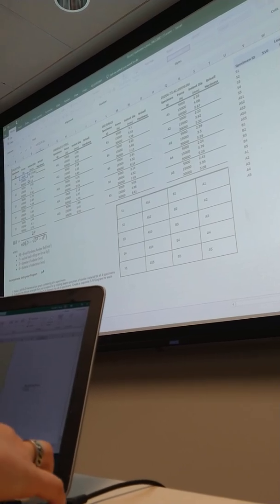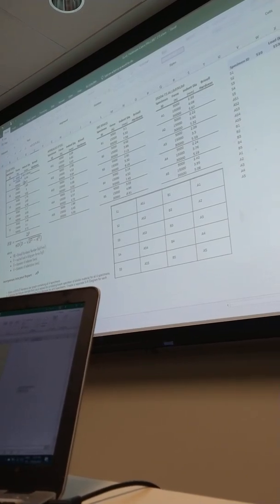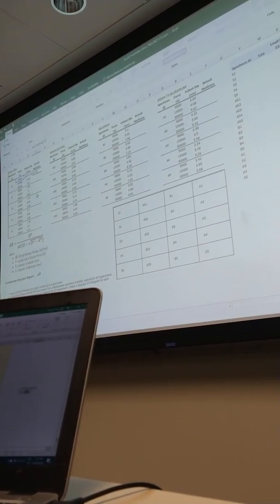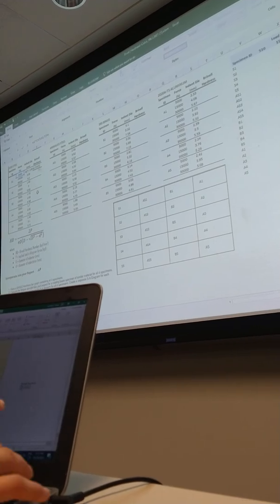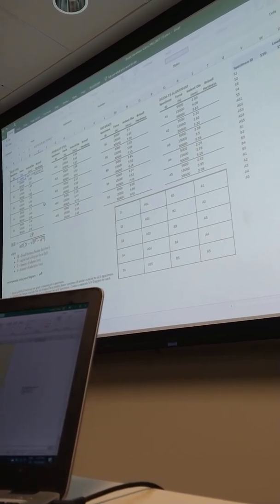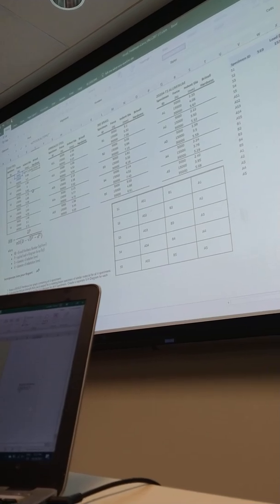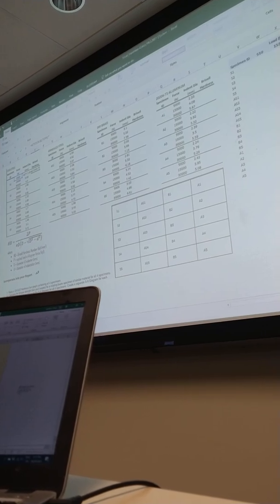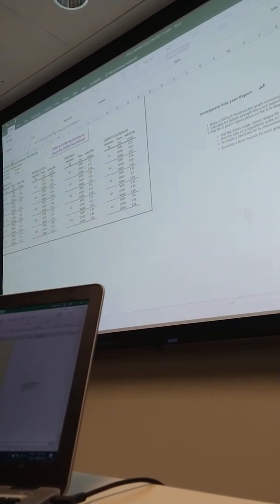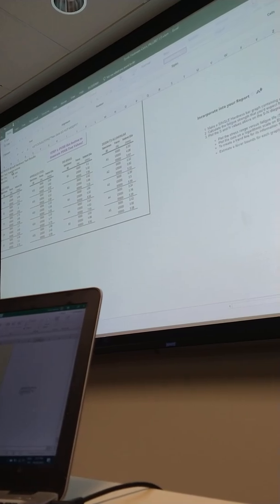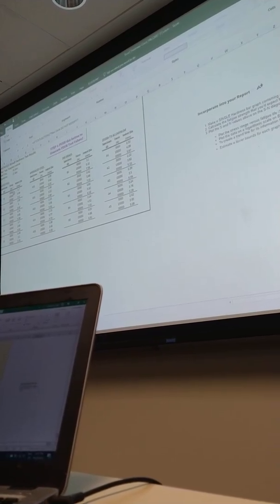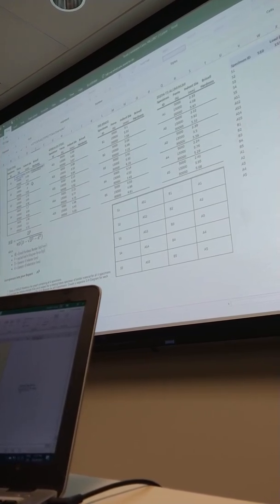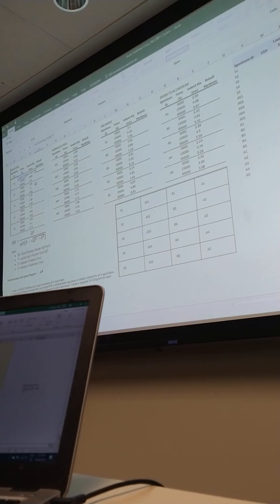So we got our force in there now. Multiply that by 2. We're going to divide by pi times our diameter. This diameter, the capital D, is the diameter of your indenter, which in this case is a tungsten ball, tungsten carbide. And it's given right here as 10 millimeters. Multiply that by 10 millimeters.